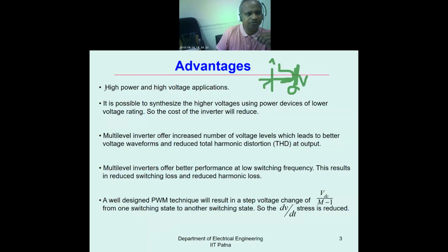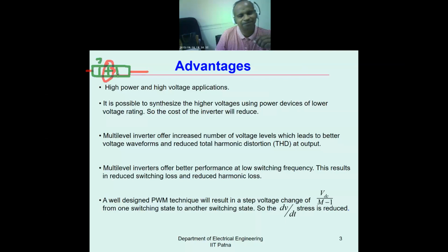And in the junction, what will it create? It will create a local hotspot. So you have PN, PN, PN, so this is one junction, J1, J2, J3. So this is the main blocking layer. So what will happen? In this layer, the charge will flow immediately, which in turn will create a local hotspot here. Local hotspot will not be known to you, but it will damage the switch immediately.